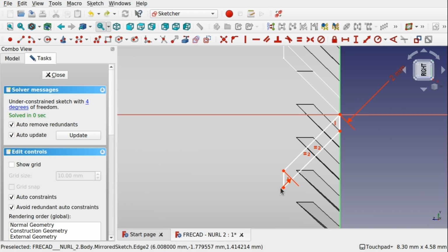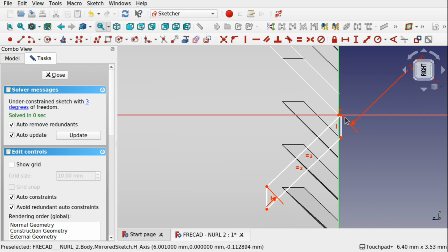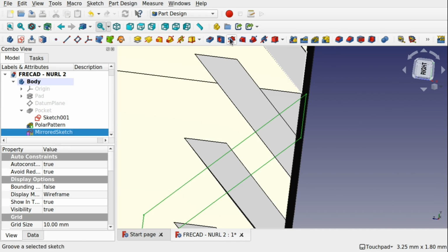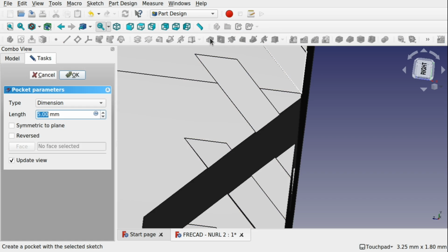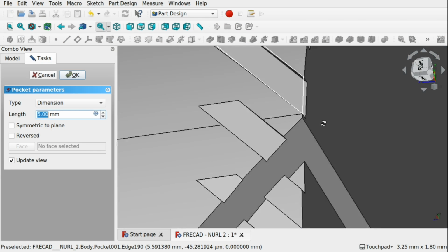We've got a length on this from here to here, and those are equal to each other. And this sketch is mobile, as you can see, but we've lost the angle constraint on here because obviously our angle constraint can't come over. I'm just going to nudge this slightly this way, just to off that point, and perhaps place that on here with a point to an object constraint like so. I'm going to close that. I'm going to try pocketing that now. So just click on the pocket. We can see that has pocketed. So that is our problem.